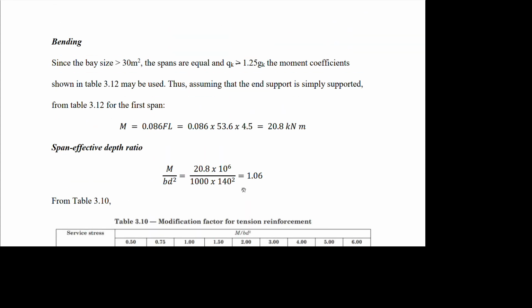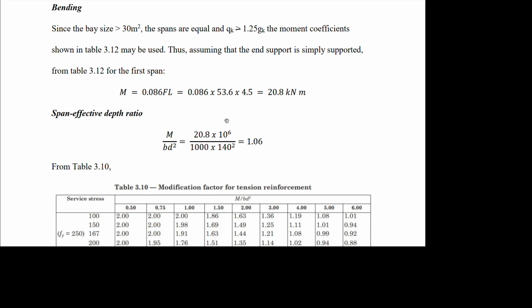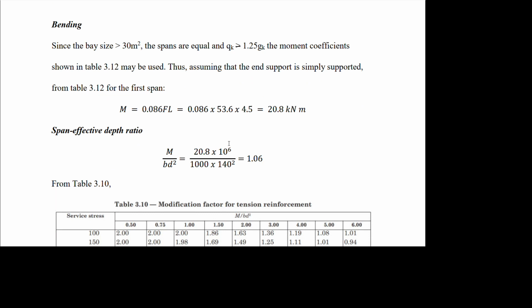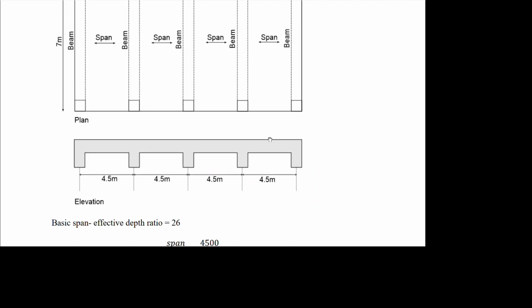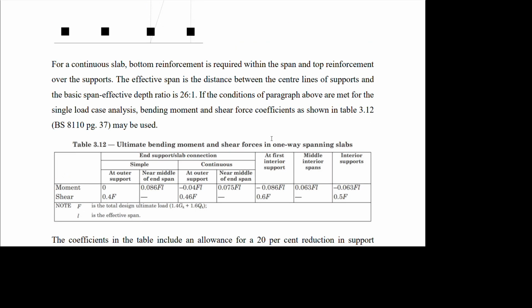Now the first thing we try to do is look at the moment. For the first span, the moment is 0.086 FL, and if you do that, let me just show you on the table. The first span,